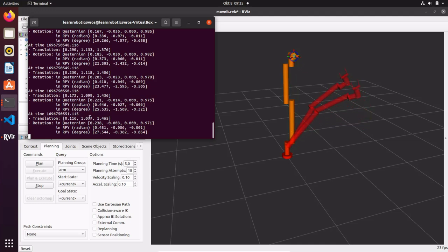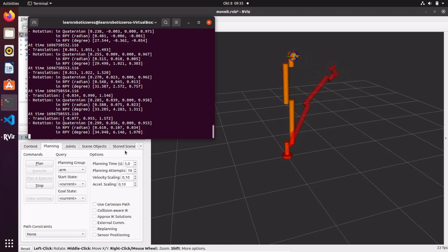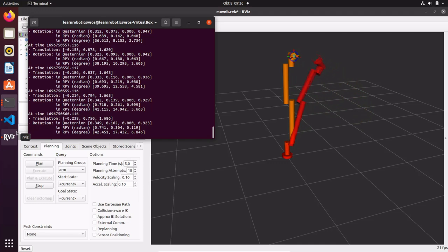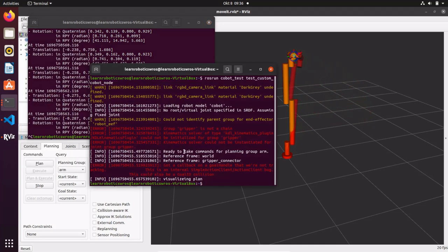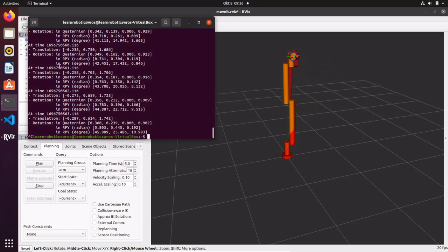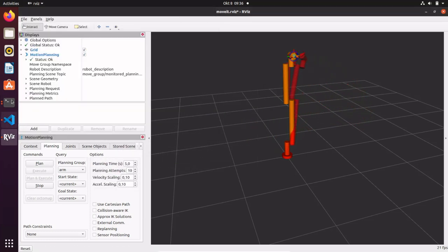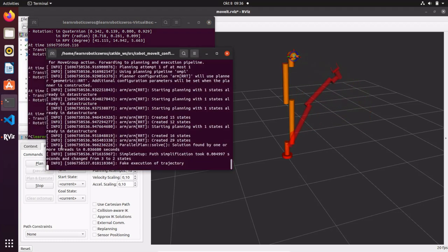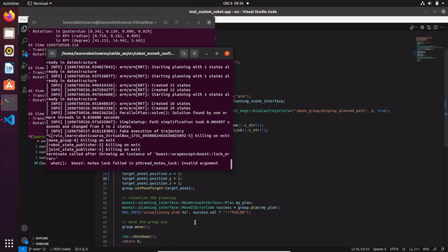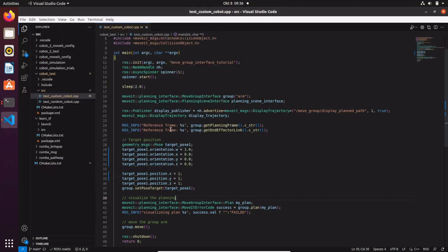And I'm going to provide the link in the description down below, but you need to know that if you have a frame that is rotating with respect of another, you need to solve a matrix, or better the orientation matrix, that has 9 parameters contained in the rotation matrix. Quaternions, on the other hand, have 4 parameters, with the drawback that it's difficult to visualize a rotation made with quaternions.